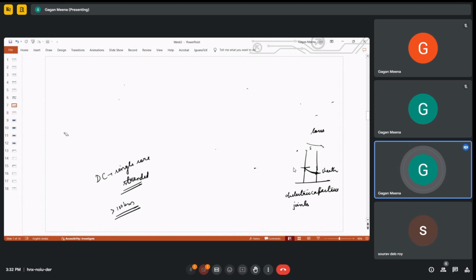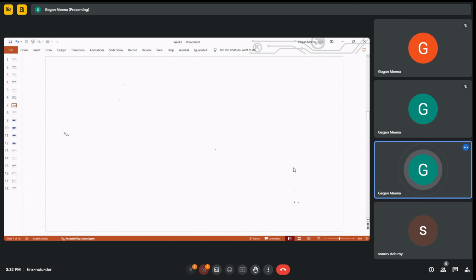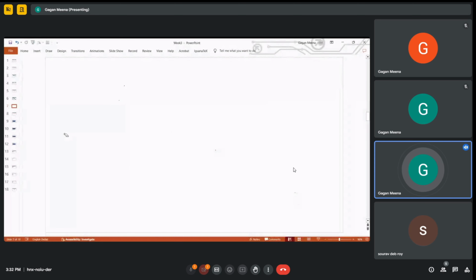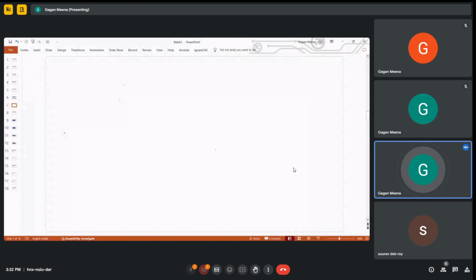An example of such transient phenomena is voltage or current surges. A voltage surge can be introduced by a sudden change in voltage at any point in the power system, and its velocity will depend upon the medium in which the surge is traveling. Such a voltage surge is always associated with a current surge also.